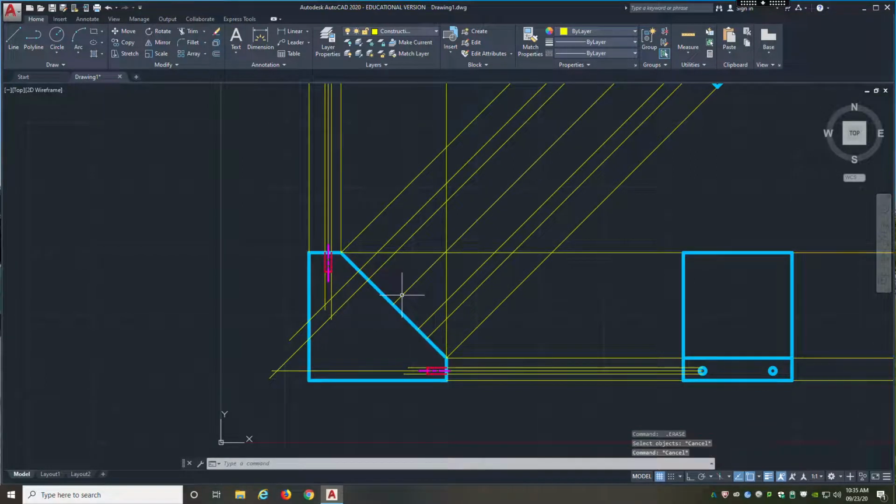Click, hover, choose lengthen. Escape. Click, hover, lengthen. Drag it out. Click, hover, lengthen. All right, so now it looks like we've got some good line work, and we'll be able to use these on our right view and also on our top view.